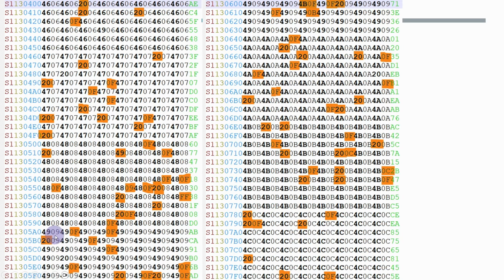And the irony is the writing to the video data is absolutely fine. It's the reading that is the problem. So I've come to the conclusion there is a 32-byte cache in the video card for reading data. And all I can assume, because the writing works okay, is that that cache for some reason is not working properly. So for the moment, I'm going to park this.